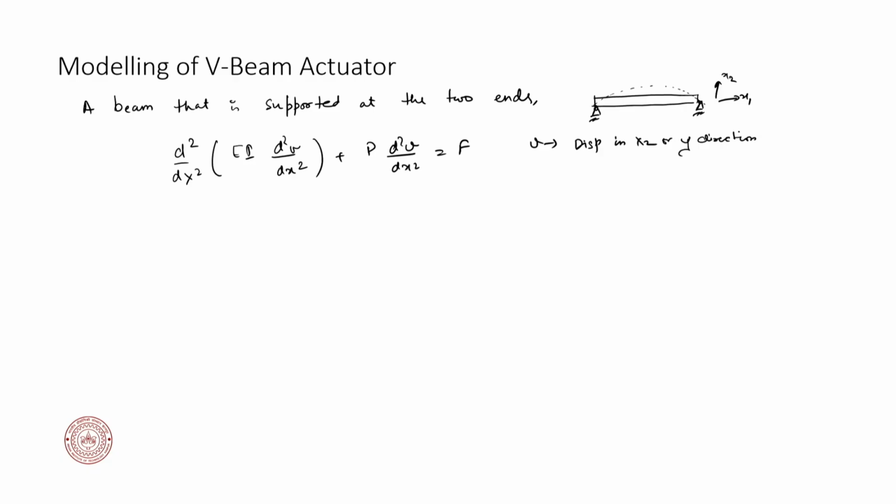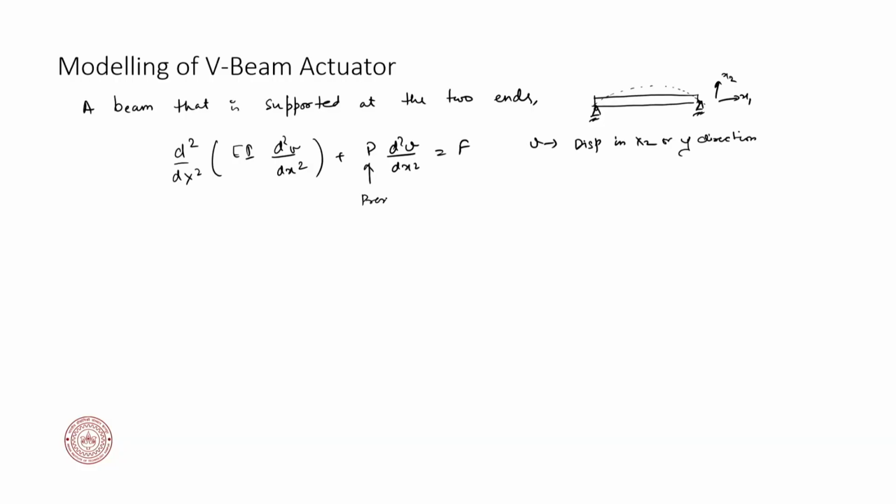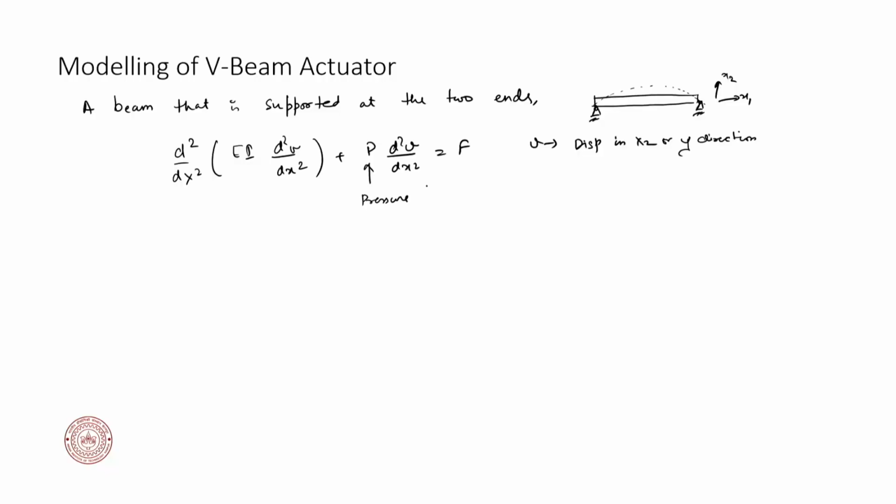Okay. Now, this is a slight modification from our linear system. We have this additional term that is due to the bending effect apart from the stretching effect. P was initially, we had a minus mu term. If you took it to the right hand side, that minus mu term is due to the pre-tension in the body. The tension can be replaced by a plus P term, and that is a pressure force. So, this is a pressure force or the inherent pressure. Say I have compressed this and I have pinned it together. Then that internal pressure or the inherent pressure is this pressure force. The F is an external force, and this is defined as P of x minus d square the moment due to the temperature by dx square.